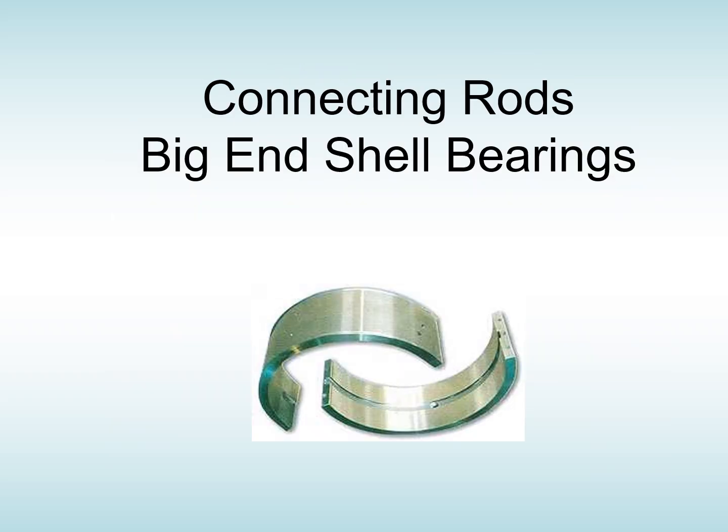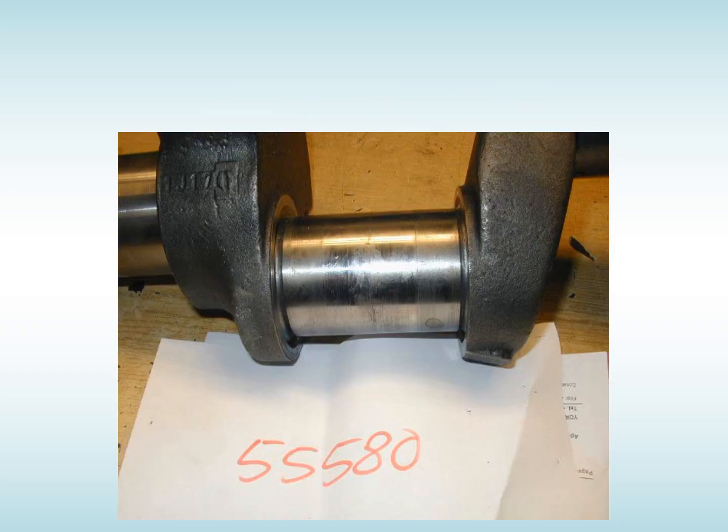Connecting rod big end shell bearings are made of a soft white metal, and they run against the crankshaft on a film of oil. Here you can see a crankshaft, and you can see where each bearing sits. So there's four rods on that one.